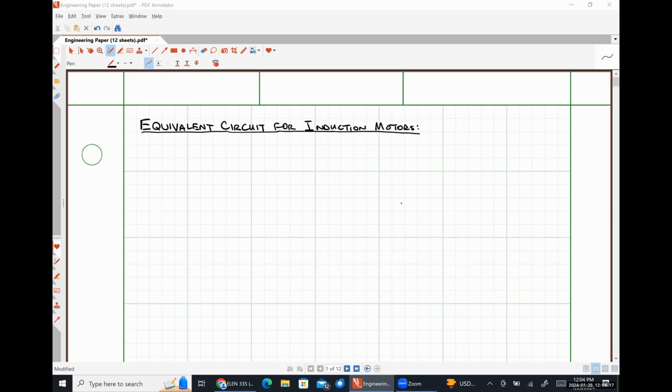So we're going to start by looking at what's going on with our stator. And actually, I need to make a note here that this is a per phase model of the stator. So there's technically going to be 3 of these, and they're all going to be electrically excited 120 degrees out of phase with each other because we're dealing with 3-phase systems. Okay.